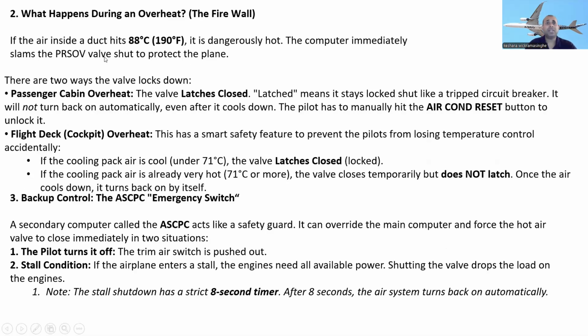So what happens during an overheat? If the air inside a duct hits 88 Celsius, it is dangerously hot. The computer immediately slams the pressure regulating shutoff valves closed to protect the plane.